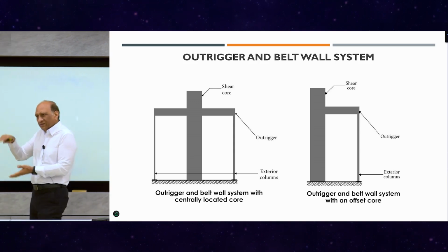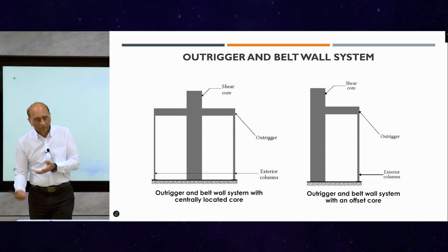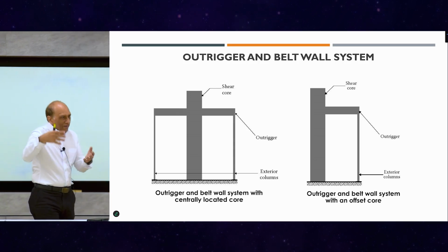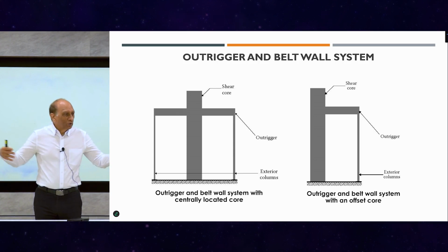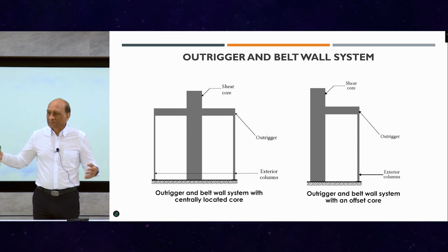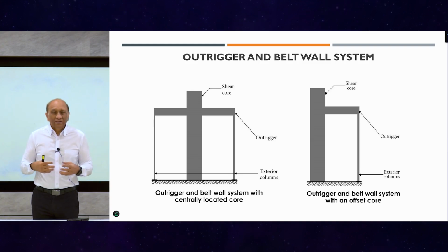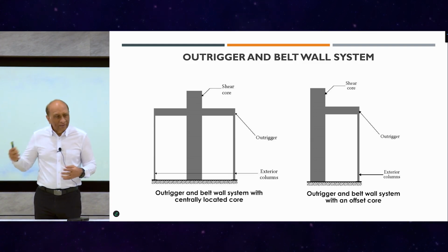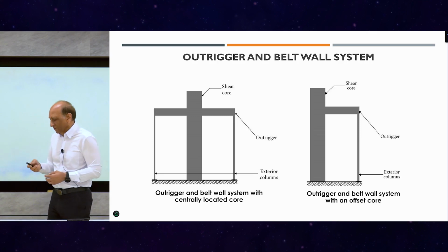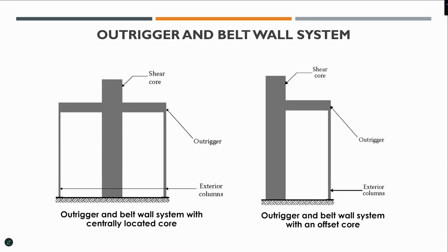And more normally it's in the middle, so they can service the floors below and service the floors above. And we normally go back and request the mechanical engineers, can we use your floor to put these outriggers? Because your pipes can go through, but we mostly utilize those service floors to put these outriggers if they are big enough. And there's so many alternatives, and today we will discuss all of them. But the concept is this one.